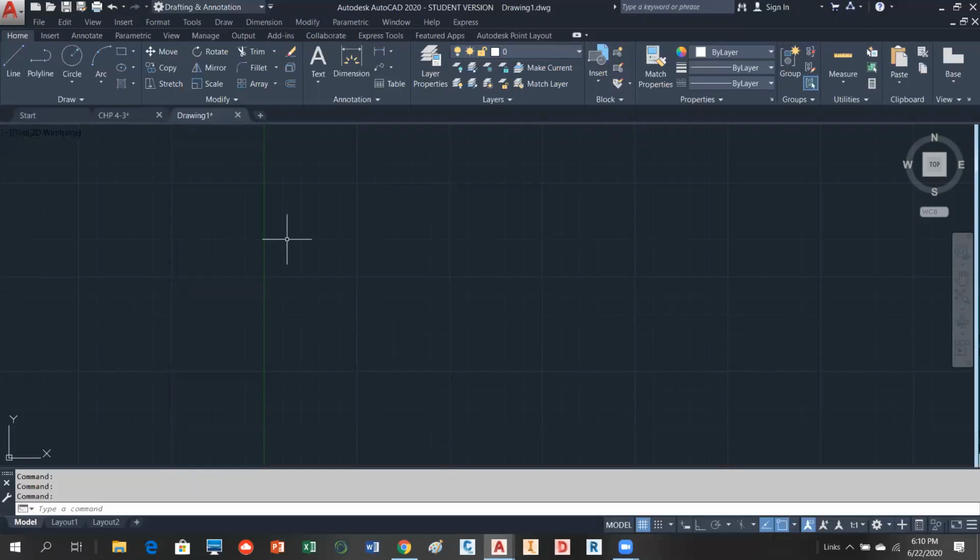assignment that we're going to be working on is talking about the UCS a little bit. And that's this icon down over here, okay? So the UCS is basically just a little icon that shows us the direction of positive X space, which is going in this direction, positive Y space going in this direction, and positive Z, which is coming towards you, and that's what that box is indicating. So positive Z is heading towards your direction.